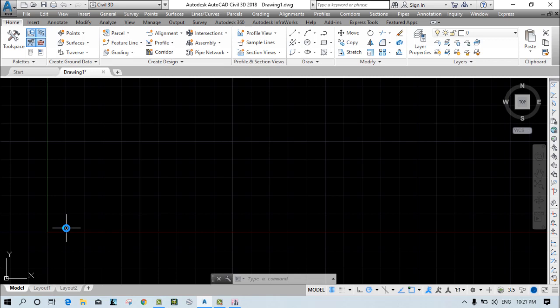So what you have to do is draw the center line plan as per your two-dimensional plan, not the three-dimensional plan they provided. Only the 2D plan I'm talking about, which is a floor plan. After that, if there is a requirement of a beam, you should tell them that yes, there is a requirement of the beam. Now I'll tell you what patterns you should follow, where you need to cut the beam and where you need to cut the column. That is also an important thing in the preparation of this normal plan.